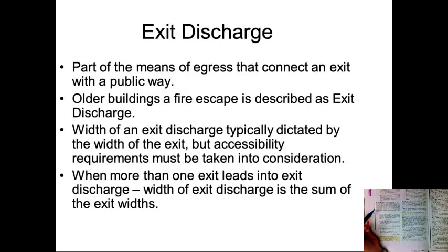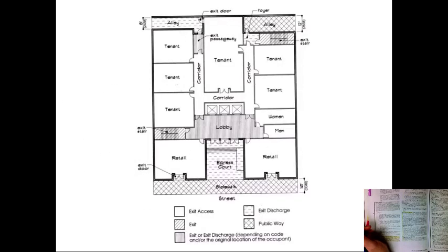Remember exit discharge. This is kind of a review. Part of the means of egress that connects an exit with a public way. In older buildings, a fire escape is described as exit discharge. Width of an exit discharge is typically dictated by the width of the exit, but accessibility requirements must be taken into consideration. When more than one exit leads into an exit discharge, the width of the exit discharge is the sum of the exit widths. Okay, very important. That means it's going to enlarge normally if the number gets there.